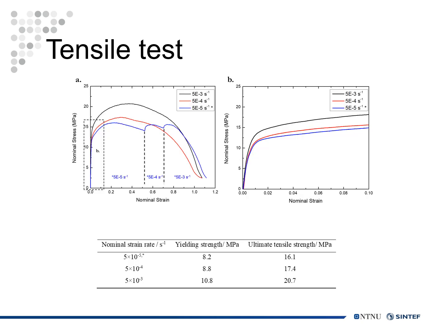This slide shows the tensile properties of the tested lead alloy. A featured result is the strain rate dependency of this material throughout the whole tensile test. A faster strain rate will lead to a higher stress level. That's why we concluded different yield strength and ultimate tensile strength values from the tests with different initial strain rates. Another interesting fact is that if we change the strain rate during the test, the stress level will also change accordingly, such as at this critical point and this critical point.